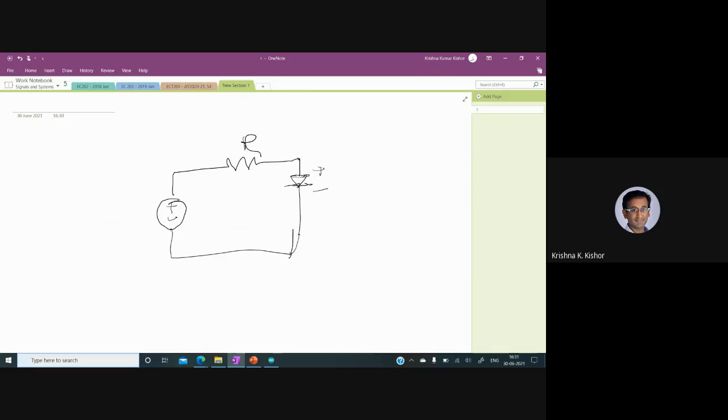The circuit diagram is always useful because we can use it for wiring our circuit. So we need a power supply, we need a resistor, and we need the LED as well. Why this resistor is there is so that you can limit the amount of current flowing through the circuit. Because if there's too much current, this LED will blow up, because there is a maximum current rating for this LED, so you cannot blow up that component.